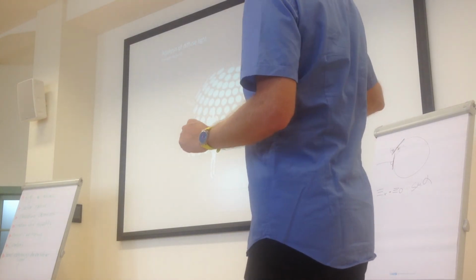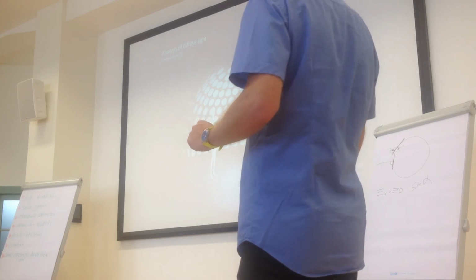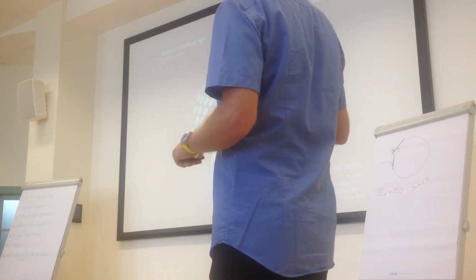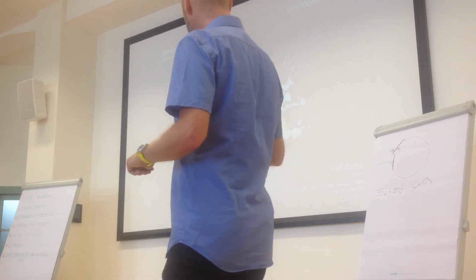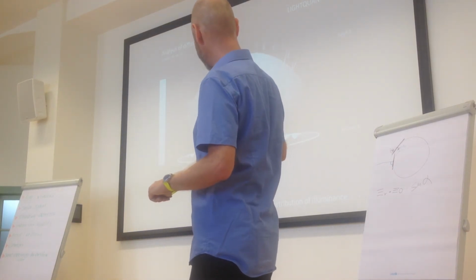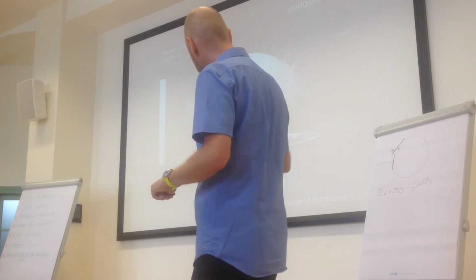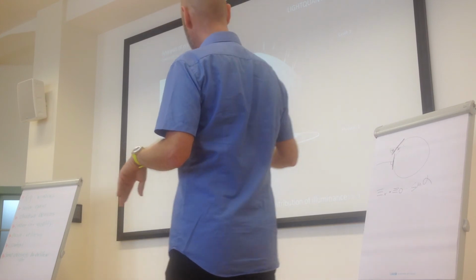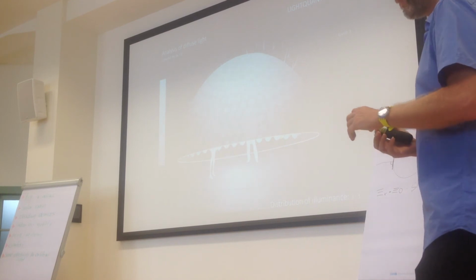The light lab itself is nothing else than a half dome with a diameter of about 6 meters. And on this half dome construction, 230 halogen bulbs are mounted, 230. And these bulbs are driven in a way that the light intensity at the zenith is three times higher than down here on the horizon. So we are talking about a 3-to-1 sky. And this is the characteristic of a constantly overcast sky.